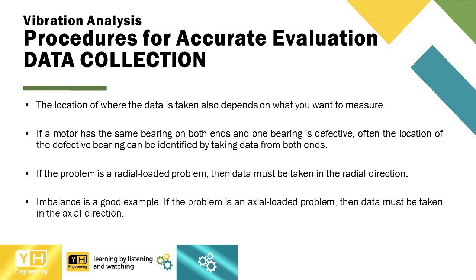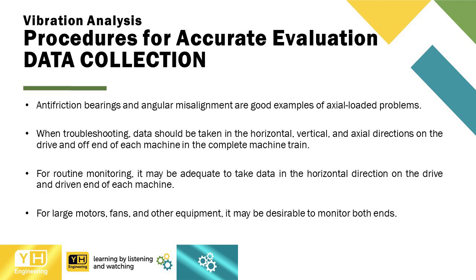If the problem is a radial loaded problem, then data must be taken in the radial direction. Imbalance is a good example. If the problem is an axial loaded problem, then data must be taken in the axial direction. Anti-friction bearings and angular misalignment are good examples of axial loaded problems.